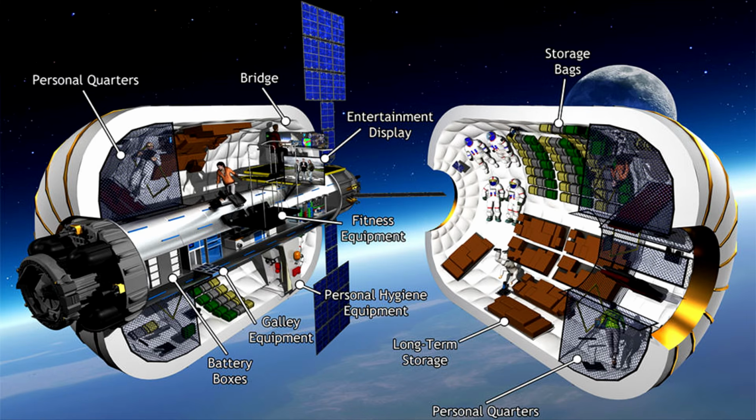It doesn't make sense for cargo. Cargo doesn't care how tightly you pack. Well, okay, it generally doesn't care how tightly you pack it. It doesn't need to have the same level of environmental control. So those could be sent direct, and you do pay a delta V penalty to hit the cycler and be able to rendezvous with it and then undock from it. But for cargo, if you're sending it direct, there's no reason to send it up to a cycler. So it may happen if you regularly have this kind of transit going to and from Mars. But that would require a serious number of people going to and from Mars.